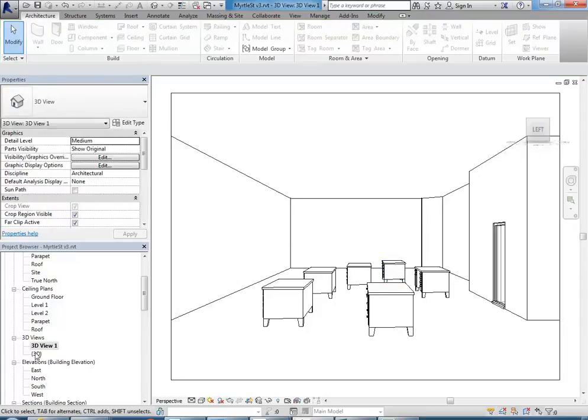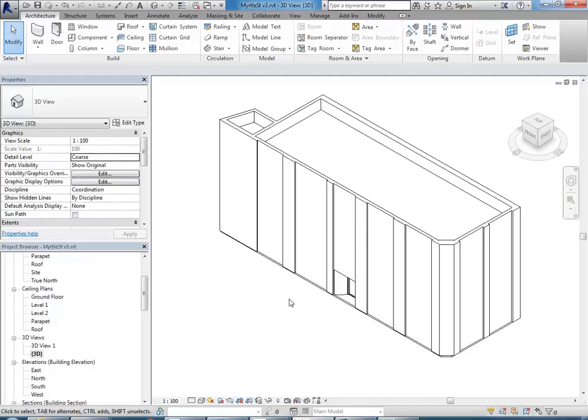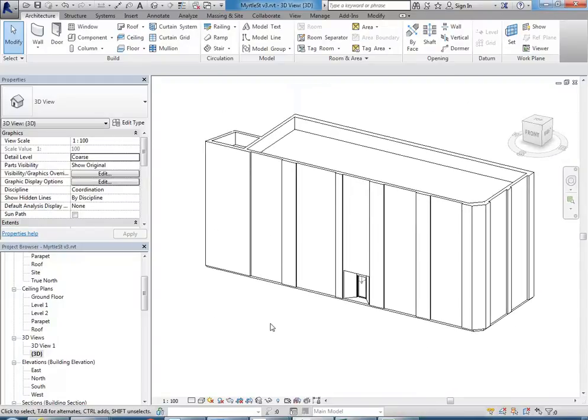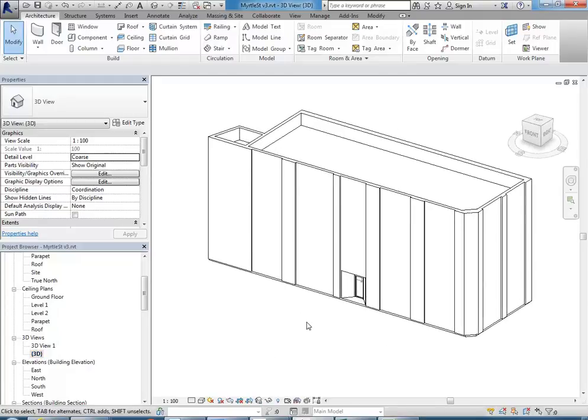Okay, so I also want an axonometric view, or isometric, but really it is an axonometric if you change the angle. And so remember, that's the view you get when you click on the house and make this one, it's called your default 3D view, the 3D in brackets, which remember is not in perspective. So I want to have a view that's like this, but showing the interior.